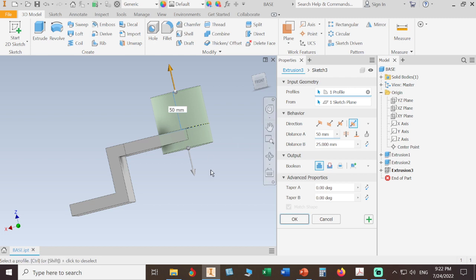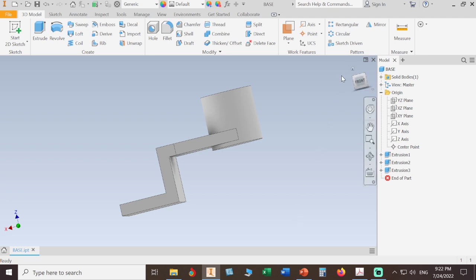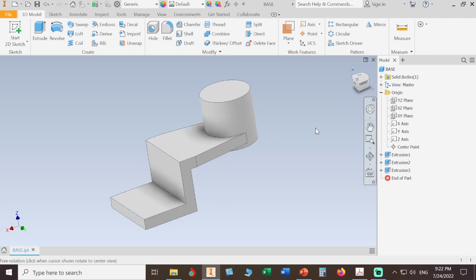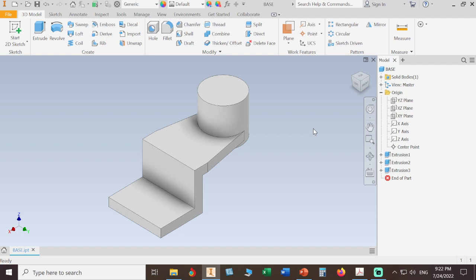It will make another extrude from the plane there. We have 15 plus 5, it's 20. This is a distance, 50, and the second distance will be 20, and hit OK. So we create 2 extrudes in one command, okay, in one feature. Good.